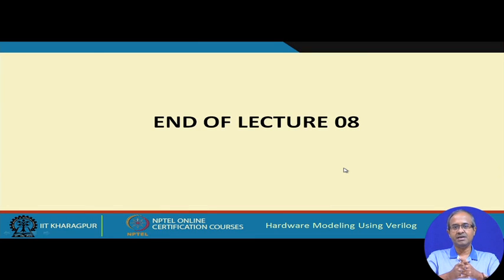So, with this we come to the end of this lecture, where we have again looked at some of the Verilog constructs, and we shall be continuing with the discussion. There are a lot of other things to discuss also. We have looked at the different ways of assigning values to variables. One is using the assign statement, another is the equal to statement, another is less than equal to. So, what are the differences between these? Assign you have already seen, but what are the other two? We shall be seeing this in our next lectures.